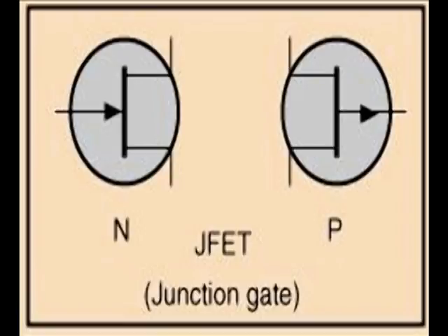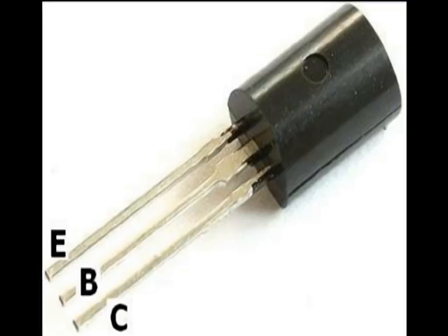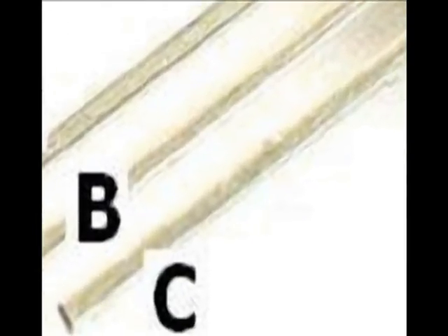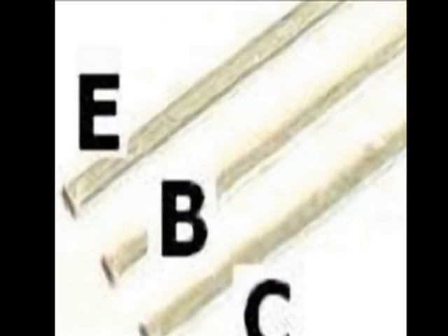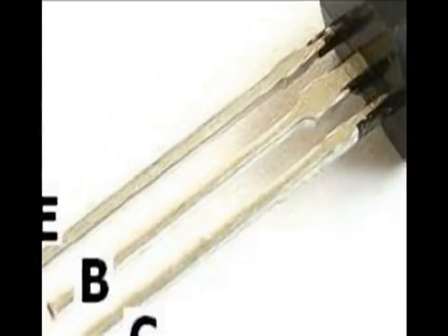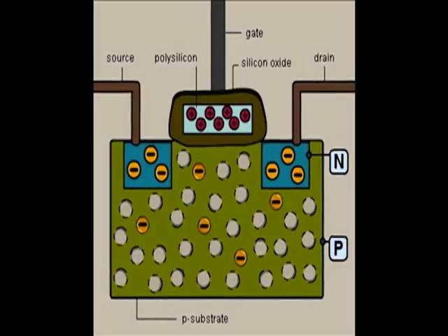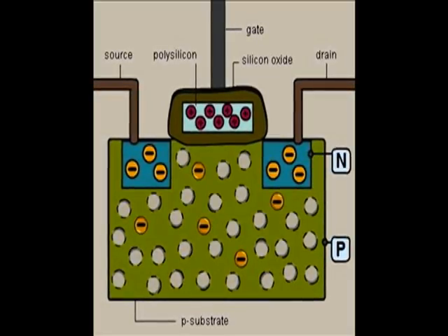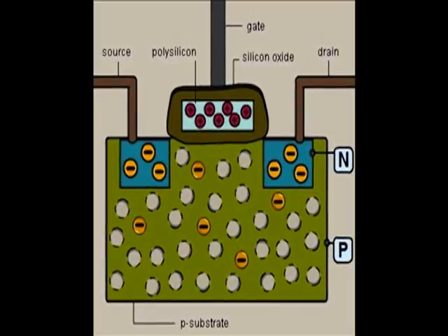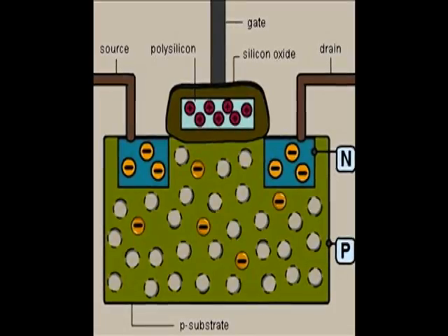A transistor is a semiconductor device with 3 connections, similar to the vacuum tube. The device includes an emitter, which is negatively charged, a collector, which is positively charged, and a base, which is varied in voltage or current to affect the current flow through the device. Since transistors are made from semiconductor material, their conductivity can be affected by varying the concentration of charge carriers within them. A charge carrier is either an electron, which has a negative charge, or a hole, which is a lack of electron, which represents a positive charge.